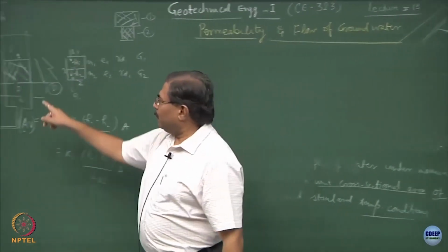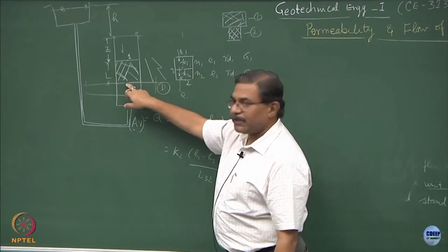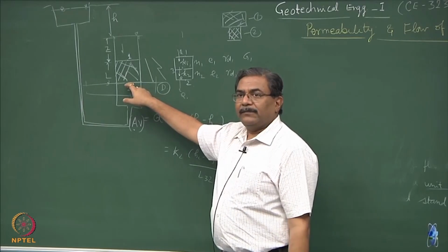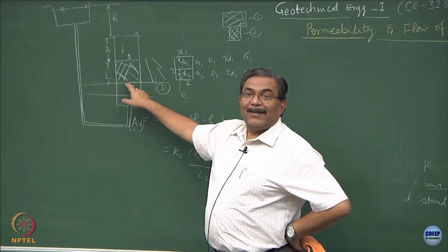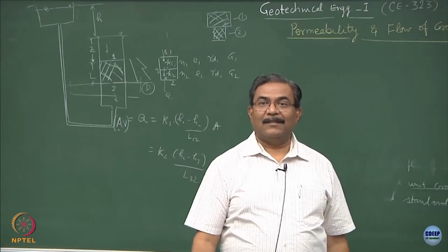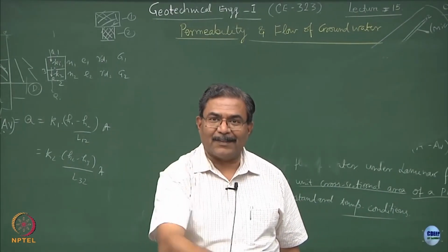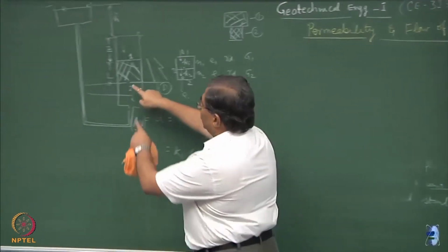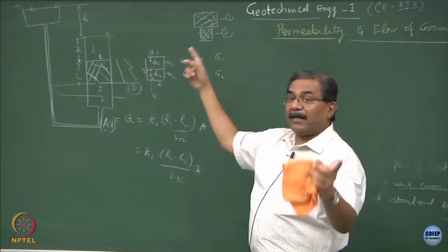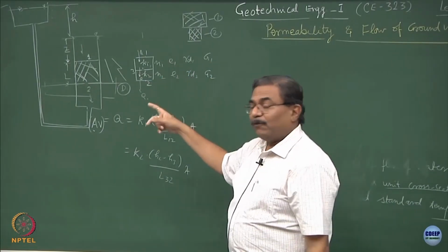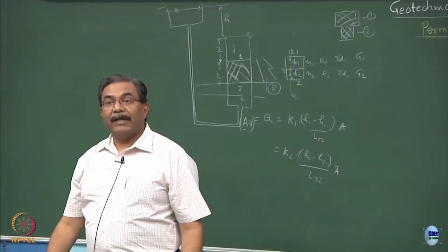Is this okay? So, if this point is being sucked with a suction pump, what will be the pressure at this point? Minus that value. So, what happens to the hydraulic gradient? This is a good question. If you suck something, what happens? Now, he is getting realization of what we are discussing, the discharge increases. So, minus of this thing and this minus of this thing, that means the hydraulic gradient is going to become higher, clear. So, V is proportional to i. That means the movement of the fluid through this porous system will get enhanced.